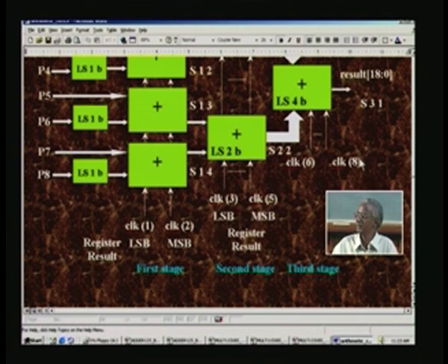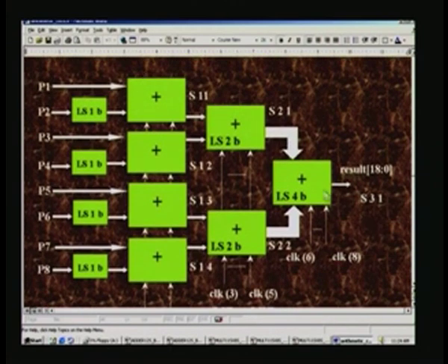Internally there are pipeline registers here, and there are basically 3 stages of addition, and also there is a shift happening inside here. And in Verilog shifting is very easy, we have only to take the relevant bits, and therefore the whole multiplier is reduced to mere addition, nothing more, or primarily addition, because even the sign in 2's complement is taken care of by mere addition, and so the algorithm turns out to be very straightforward and simple.